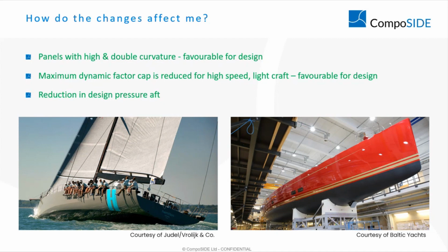Acceleration and pressure as another example. An acceleration cap has been added and longitudinal pressure distribution has been modified following industry feedback. Those bring better control of the maximum design pressure load and more realistic lower design pressure towards the aft end of the boat.